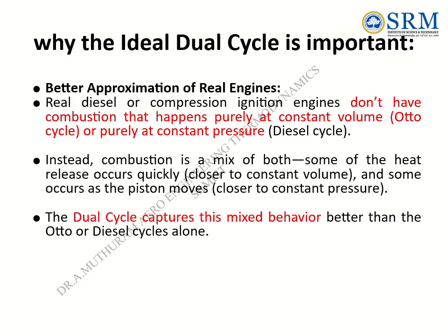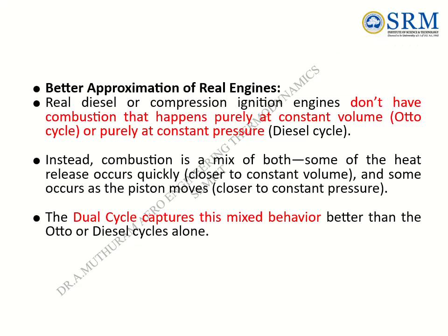Why the ideal dual cycle is important. Real diesel or compression ignition engines don't have combustion that happens purely at constant volume, Otto cycle, or purely at constant pressure, diesel cycle. Instead, combustion is a mix of both. Some of the heat release occurs quickly, closer to constant volume, and some occurs as the piston moves, closer to constant pressure. The dual cycle captures this mixed behavior better than the Otto or diesel cycles alone.